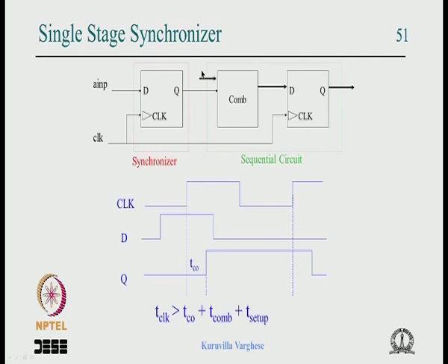So with the random behavior of this input, we are sure that one or two can get into metastability, say. I say it under quotes, because we have to really see the probabilities, which we have no time to analyze in this class. But I suppose you get the picture. The situation is improved because we put a single flip flop and sample with it. It is tightly controlled, there is no path delay, it is directly coming here, and if at all a flip flop gets into metastability, it is this flip flop, not all of these, okay.